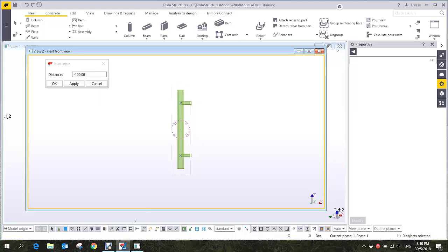Because the name is something like the code. In the code the name is there, and then the height and then the thickness, right? So the code and then the quantity, that's most important. Even if you want to model this one, you don't really need to put the exact shape. You just put the representation of that particular item. Much easier for you. You don't need to spend much time.